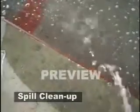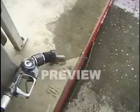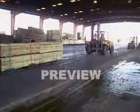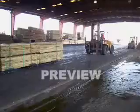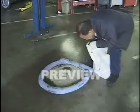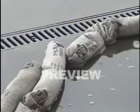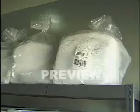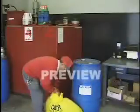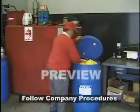Spill cleanup. It is the vapors rather than the liquid itself that burn. When the liquid is spilled, vapor release begins immediately and continues until the liquid is removed. This requires that cleanup operations begin at once. Specially developed absorbent materials are available for spill cleanup. These products are offered in pillows, pads, sheets, tubes, and other shapes to fit all cleanup needs. Once the absorbent material is saturated, it should be placed in a large disposal drum and sealed with a drum cover.